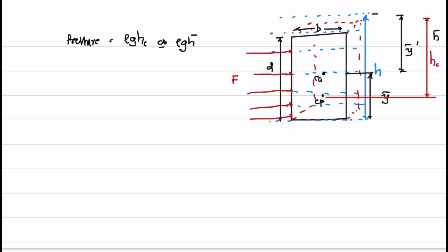Now, what is the force? Force is equal to rho g h c into area, or rho g h bar into area of cross-section. This is a very, very important equation.